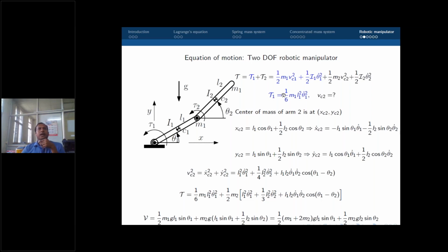Now, when we hinge that rod at some point on the plane, what happens? We restrict its translations. That hinge point restricts its translation in any direction. It cannot translate, because the hinge point is fixed. It can only rotate with respect to that hinge point. So what is left? 1 degree of freedom. So the system here has 2 degrees of freedom, and the generalized coordinates are theta 1 and theta 2.